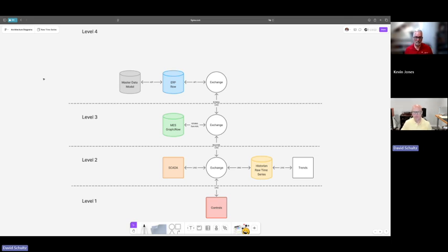So a couple of things about the historian. It's raw time series. This is going to be a very specific column-based type data set that you'll see within the process historian itself, because we're constantly moving. The domain is time, so you're going to see that information being ingested in that more column-based approach. And then, of course, the way that you are generally consuming that information is through some kind of trend screen existing within your SCADA and or your HMI.